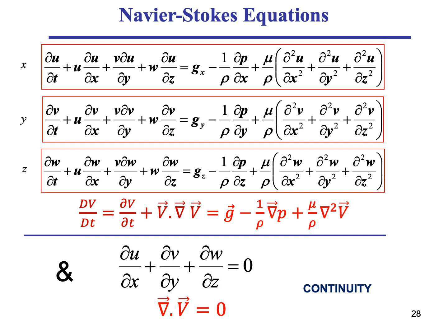And on the right hand side, we have the gravitational force per unit mass, so the weight per unit mass is just the gravitational vector. We have the pressure gradient force per unit mass, and then here we have viscosity. So these are our viscous stress gradient forces per unit mass. So you'll see forces per mass are on the right hand side, and shear stress is on the left hand side.